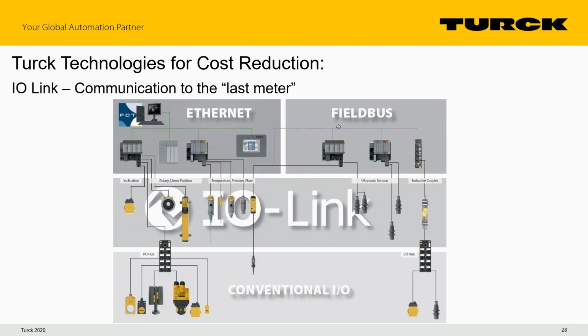We also have field bus, which is pretty much what we've been talking about this morning, is field bus devices that are IO-Link masters. And this middle section here is IO-Link devices. And this is really key because these are the devices that communicate not only their process data, but their status, their health, whatever information the manufacturer makes available is available through message instructions back to the control system. So I will pick a few examples here.